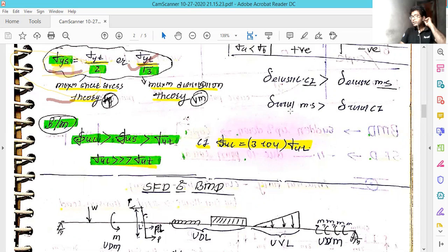But the elastic deformation in the cast iron will be higher compared to the elastic deformation in the MS steel. So there is a little confusion, because we know that the elongation of mild steel is more compared to cast iron, since it's a ductile material. But in elastic deformation, the cast iron will deform more compared to the deformation in the mild steel.